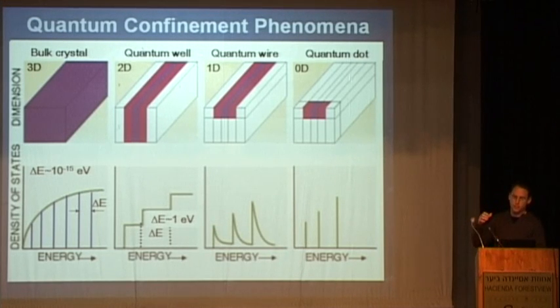It creates an exciton, which is a pair of electron and hole. And the energy between the levels can reach up to 3 to 4 electron volts, which also gives special photoluminescence properties to quantum dots. One of the pioneers of quantum confinement was Canham in 1990, who created mesoporous silicon islands and created photoluminescence from silicon. Silicon is an indirect semiconductor, so it shouldn't create photoluminescence.